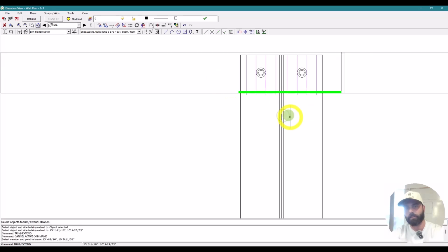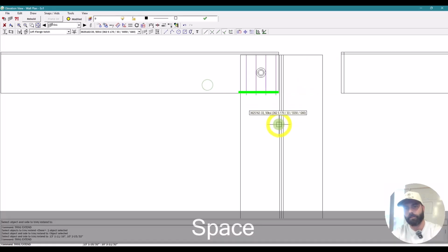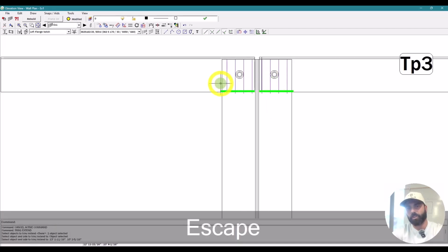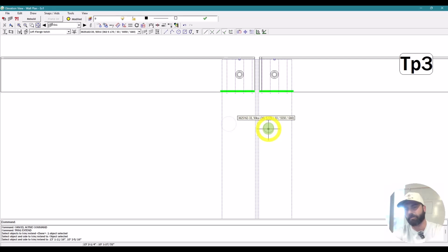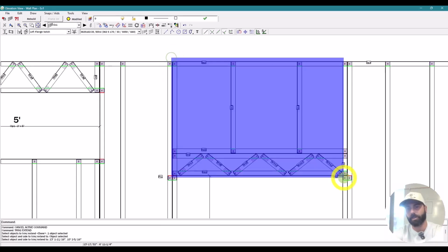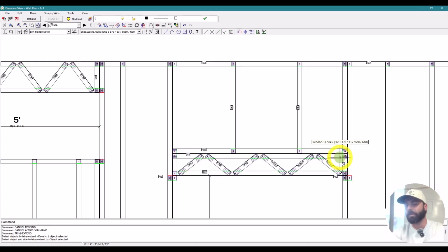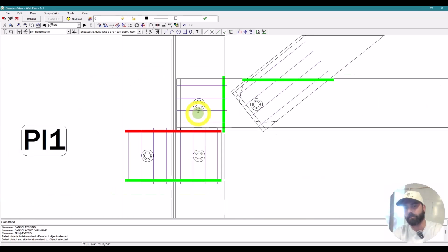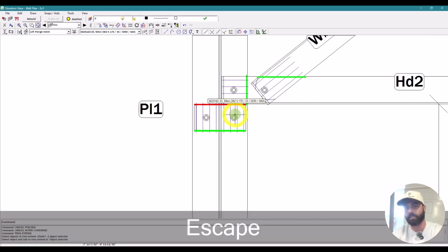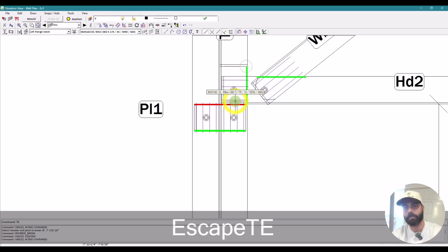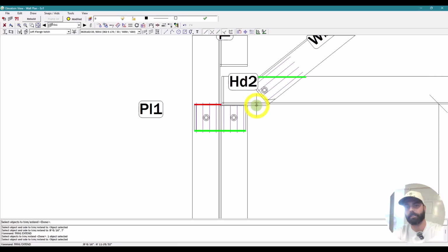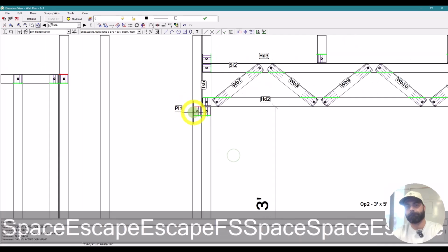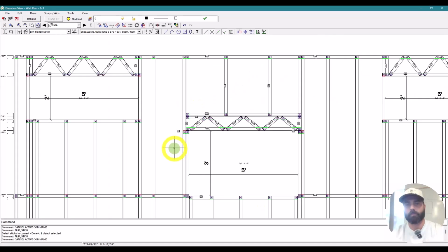So if you're working with big, massive openings, engineers, instead of relying on the strength of this screw and this webbing that would tear out, you're now relying on something that's sitting. So that PL1 is actually kind of a top plate that the header sits on top of. And I can go ahead and grab it for you guys. Yeah, we make a lot of beam boxes, a lot of truss seats, so that nobody needs it. All they have to do is use their hands. If it's flush, it's square. See that? This is its own panel that we could ship with smooth sides around the entire outside face.